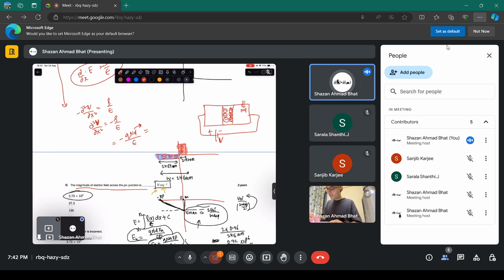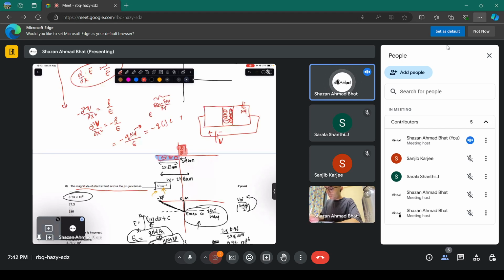How these concentrations vary is exponential of something like Ec minus Ev divided by kT type. Not exactly like this, you get basically EFN minus EFP divided by kT, which is the difference in quasi-Fermi levels, which is basically the applied voltage V.